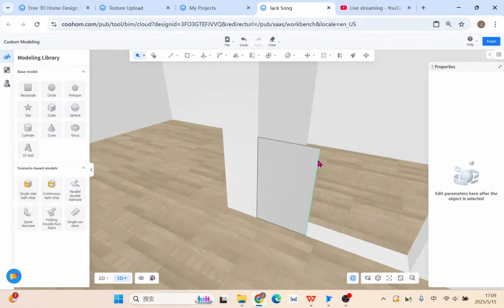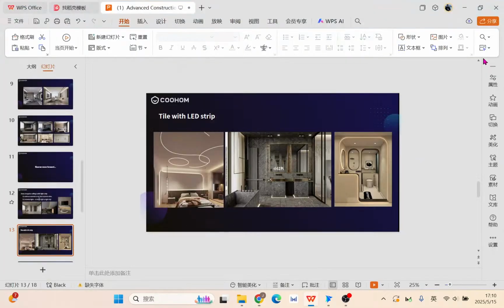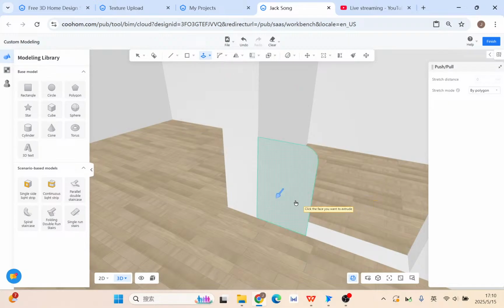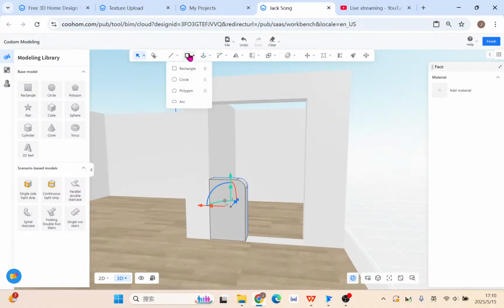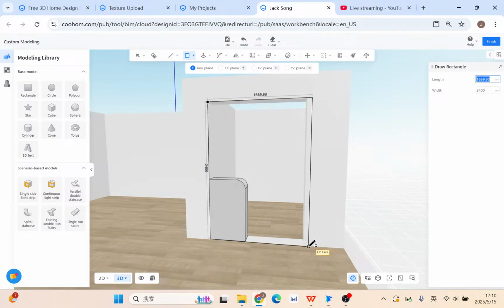Also this one, bevel, because you see we got this chamfer, bevel 2D. Okay, edges, chamfer, tuck in a very small one, 150, let's say. So push and pull. You can see here, push and pull. Pull thickness, and then rectangle, bring them back.